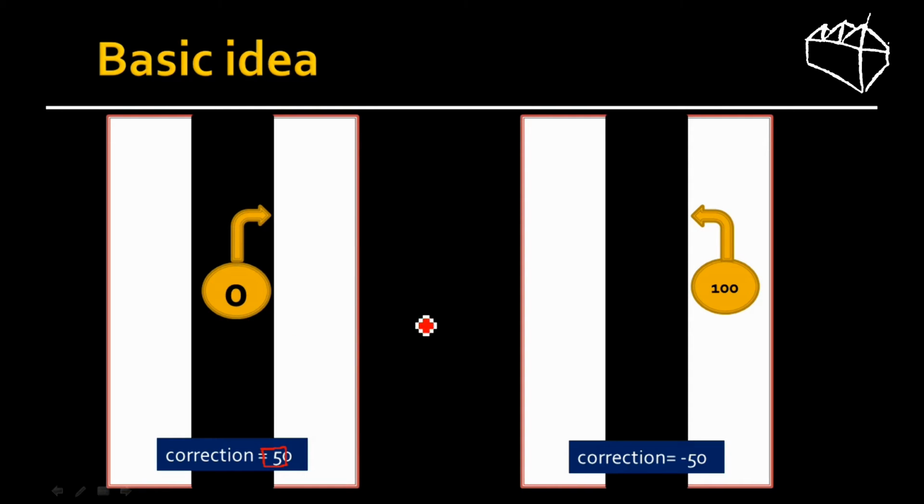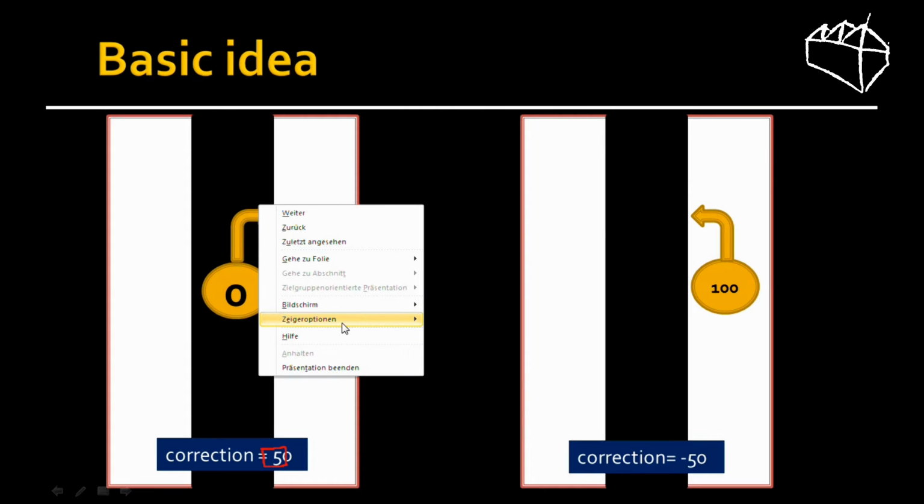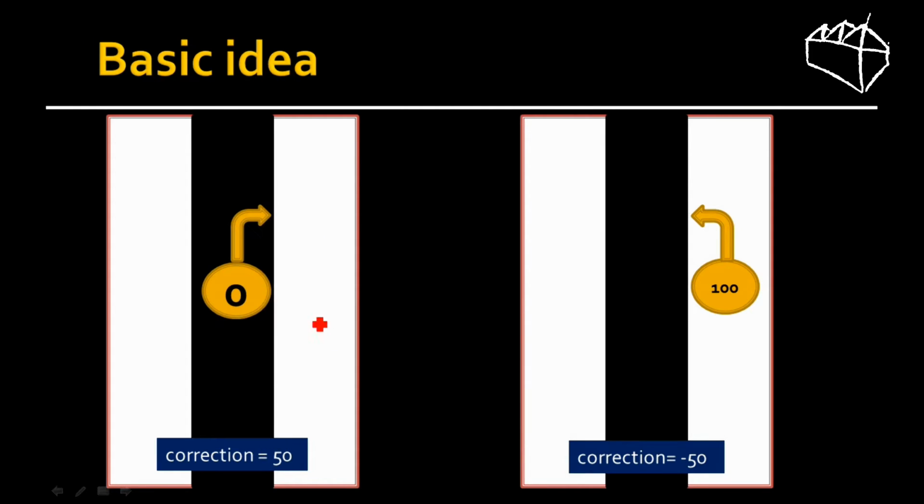The basic idea of the line follower is that you actually want to follow the edge of the line, because otherwise you don't know which side to go. For example, if your robot detects black and it drives forward, but then it detects white, it doesn't know if it's on this side or on this side.